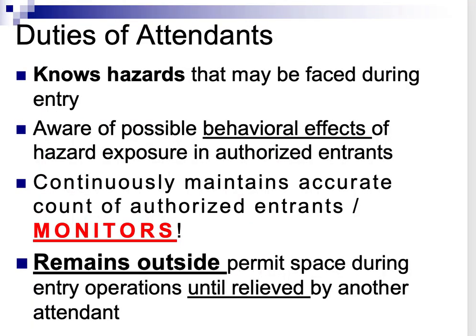So the duties of the attendant, that's the guy or the girl who's taking care of the person who's going into the space, knows the hazards that may be faced by the entry person, is aware of what kind of behavioral effects could take place if the person who is entering the confined space starts to feel asphyxiated or dizzy, or starts to get that effect like you feel like you're intoxicated, which can happen when you start to lose oxygen supply to the brain, and that's when that carbon dioxide or carbon monoxide is replacing the hemoglobin on the blood.